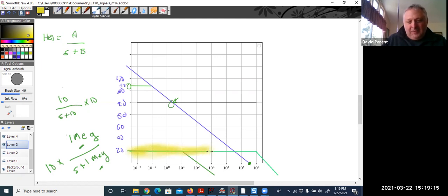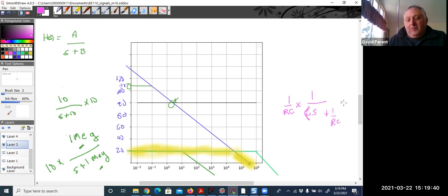All these frequencies, it works. And then you'll see a low pass filter with a wildly different gain, right? And you might say, well, wait a second, that should be 1 over RC times S plus 1 over RC, which, yeah, your resistor can maybe vary 10%, and the capacitance can vary 10%.